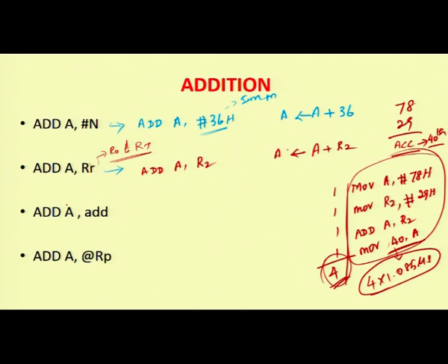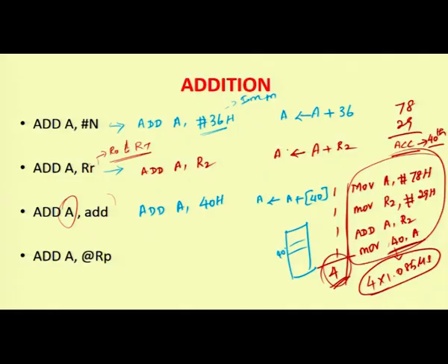So, the accumulator data is added with the address. Suppose we give the instruction like ADD A, 40h. What it represents is the content of 40 is added with the accumulator and the result is stored in the accumulator. It is like this kind of memory we have, right. So, the unknown data which is in 40 is taken and added with the accumulator. This is a memory access.